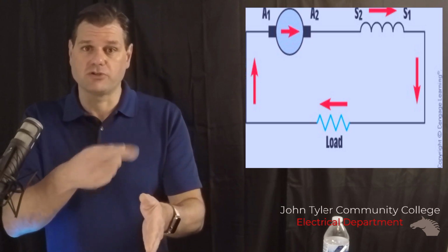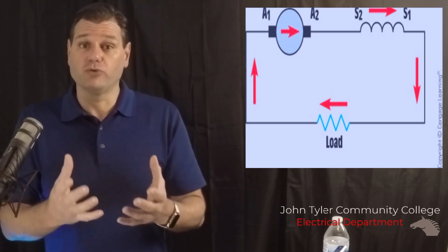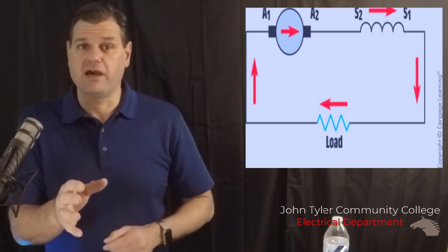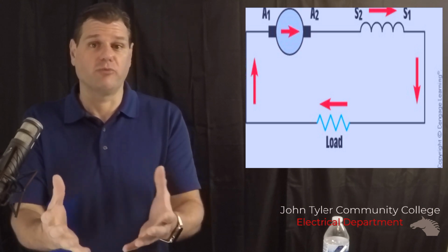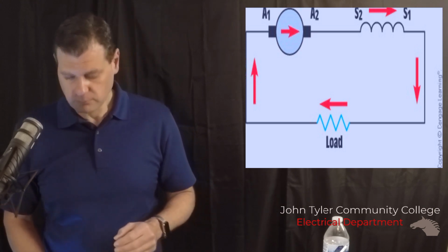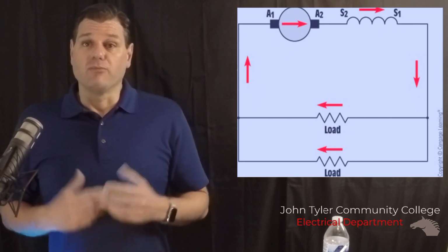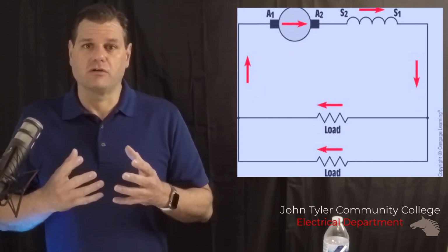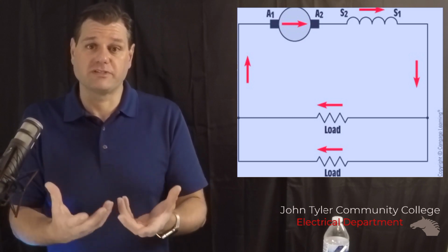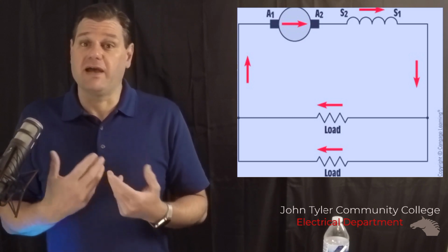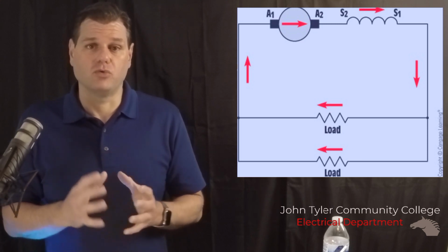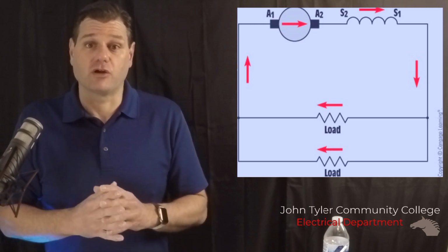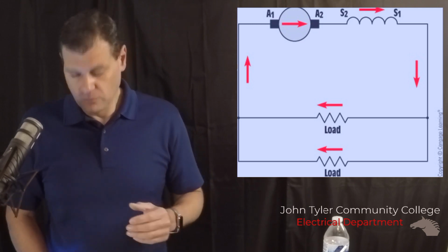So when we rotate the armature, we're going to produce a voltage by cutting the flux we talked about a few minutes ago, and we're going to be allowed to send out that voltage into our load, being whatever is plugged into the system. All right, the more load we add, the more it bogs down. You're drawing more from the system, so it's not being as efficient, and it will start to lose its production of voltage very, very quickly.